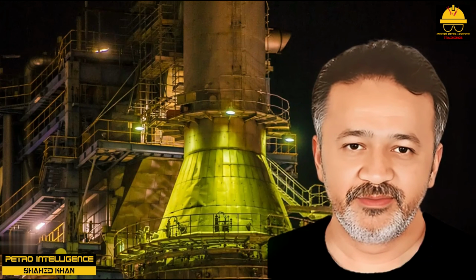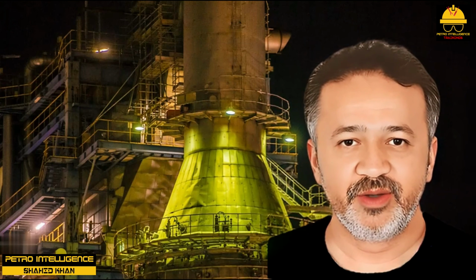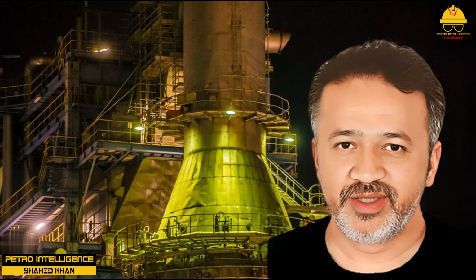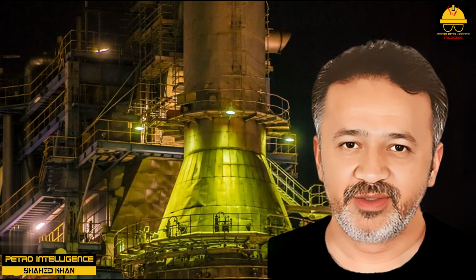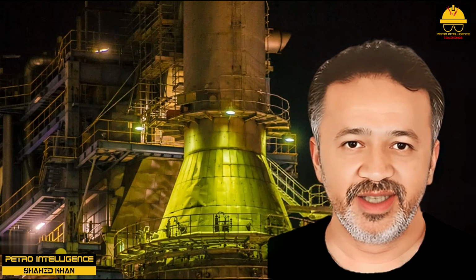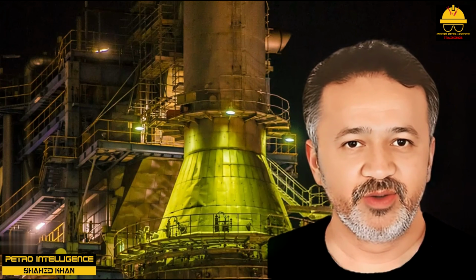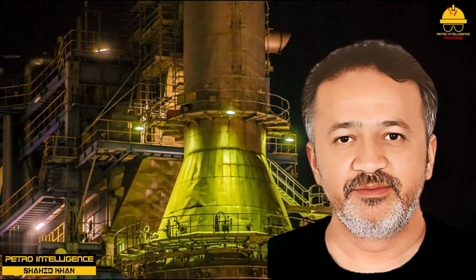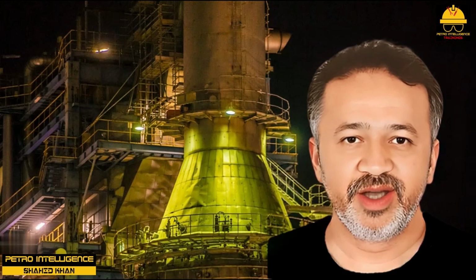Here is what happened. Preheating the air by 300 degrees Fahrenheit had raised the burner flame temperature by 300 degrees Fahrenheit. The hotter flames then radiated more heat per pound of fuel consumed, and as a result, the firebox became much hotter. The same factor that reduces fuel consumption in the radiant section also reduced the flow of flue gas to the convective section, thus reducing the convective section outlet temperature. So, what can we do to actually run more crude, especially as there is no bypass around this new air preheater? The answer, of course, is to allow more air into the firebox and thus generate more flue gas.